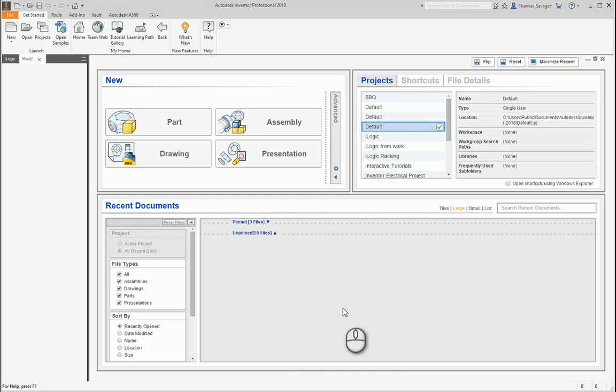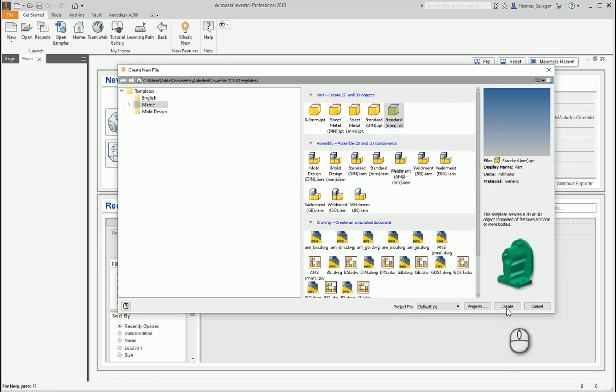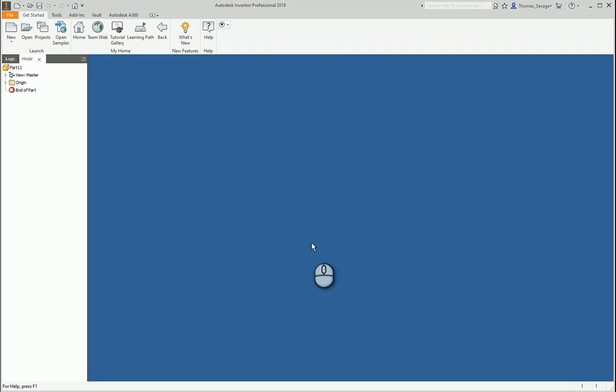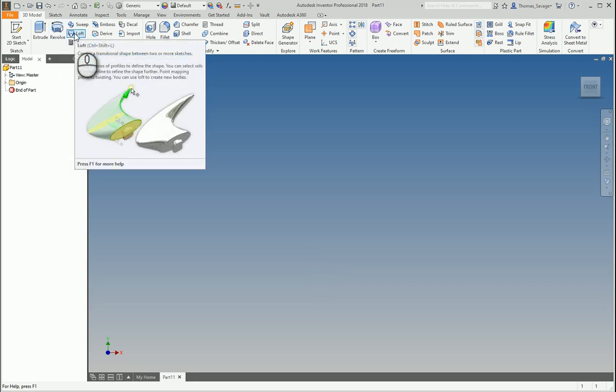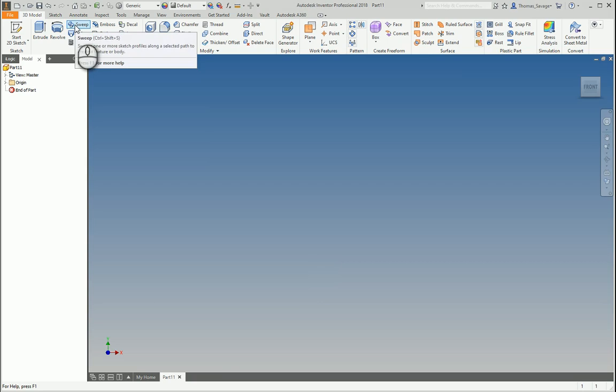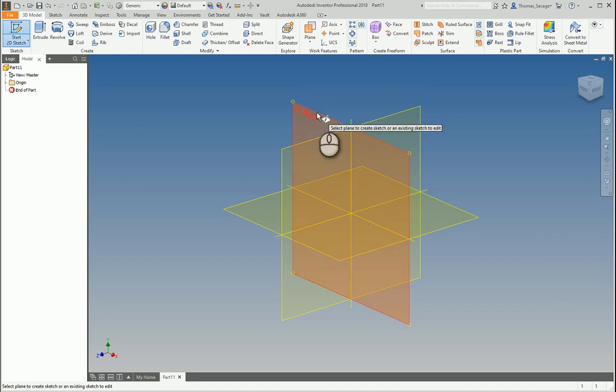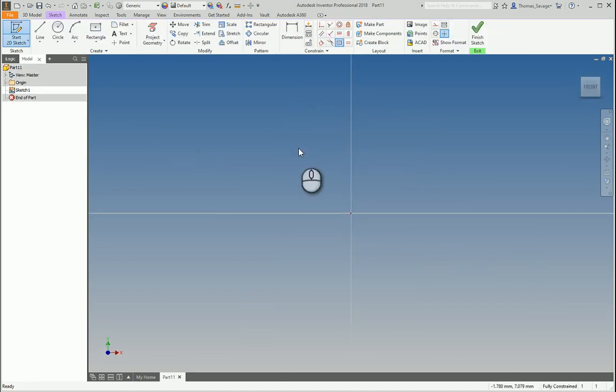In the last episode we looked at extrude, the cut and extrude, the hole feature, the fillet feature and the chamfer feature. In this episode we are going to look at some sketch constraints, briefly go through them, the Revolve, the Loft and the sweep feature. We'll look through them, starting off with the sketch constraints, just to get a basic knowledge of the sketch constraints. So we'll start a sketch.